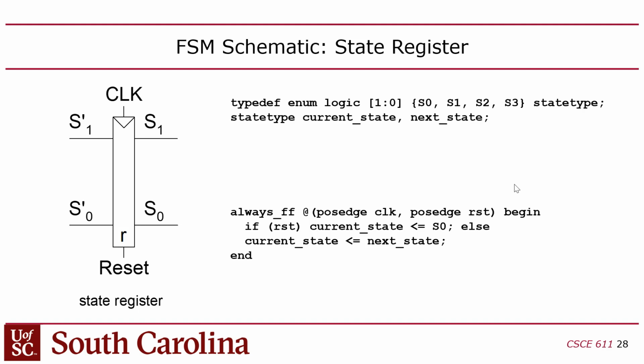You can have the English mnemonic in ModelSim, just as a debugging tool. It's easy to do because otherwise, like he was saying, it crashes when I get to the subtract instruction. How do you know when you're executing the subtract instruction? It's just the machine code, right? But if you have a little debugging feature, well, you could see it's the third instruction, so it must be subtract. But if you have an enumerated type and a signal declared with that type, you can actually have it print subtract at that moment in that clock cycle, right? You guys with me? Okay, anyway.